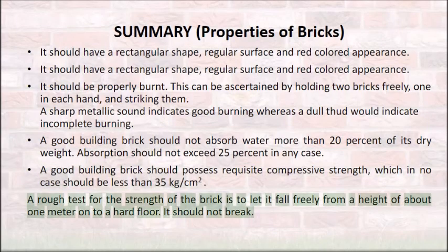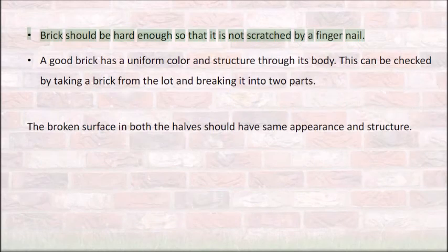A rough test for the strength of the brick is to let it fall freely from a height of about 1 meter onto a hard floor. It should not break. Brick should be hard enough so that it is not scratched by a fingernail.